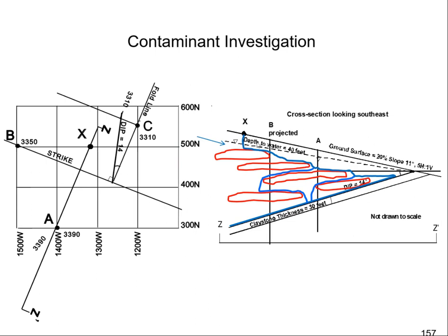And then you would go from there. But we don't have enough information to be able to definitively isolate it at a shallow depth, because a slurry wall cannot be put in all the way down from the tank site to the claystone thickness. That's about 300 feet, and that is not really a viable solution. So that by default kind of leaves us with the last answer, because we don't have enough information to really make a call on a slurry wall.